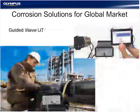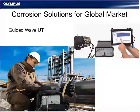From there, we have a newer system that's available. There's what we call guided wave systems. Now, guided wave is really more of a screening technology, but it is significantly more powerful in the area that it can cover, and it has some distinct advantages over some of the other products that we've already covered, in the sense that it uses ultrasound still. However, what it does is it transmits ultrasound down the length of the pipe.